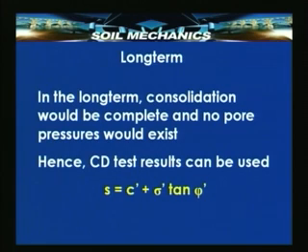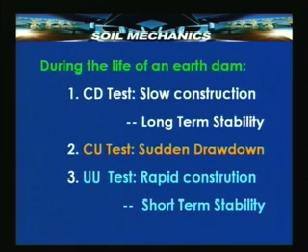On the other hand, the long term behavior, as I have mentioned already, is a situation where the construction is complete, the pore pressures have been totally dissipated, the dam is now in a condition which can be equated to the totally drained condition, that is consolidated drained, and the CD test results again can be used as we did for construction period where slow construction was permitted. S is equal to C dash plus sigma dash tan phi dash.